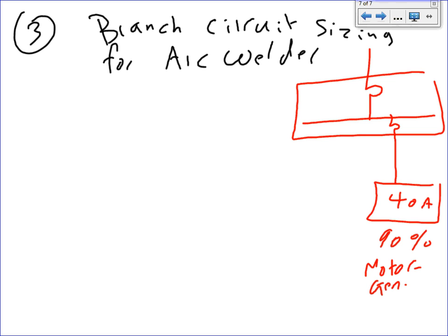Okay. Holly, what was the size of the panel, guys? Anybody remember what was the size of this panel? Just remind me of the size of the first panel that we did. 150. This was a 150 amp panel, and the voltage was 208/120 volts. So I just went to the first panel that we sized. I pulled one load, and I need to size the branch circuit for this load. Typical for all of them, guys. You're going to find it's typical for all of them.